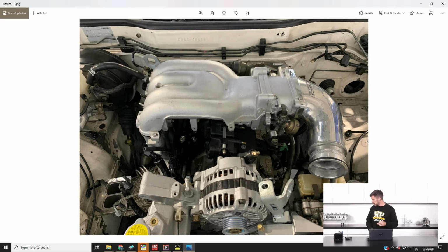What we looked at doing was using something like this, which is a remote mount drive-by-wire throttle motor I should say. This is specifically off a BMW S54, so this can drive a conventional throttle body using a pushrod mechanism, so it seemed ideal. The problem is that there weren't a lot of opportunities or locations that were convenient to mount that. I'm a bit OCD. I didn't want it to look ugly, so that's one of the drivers that we were considering.